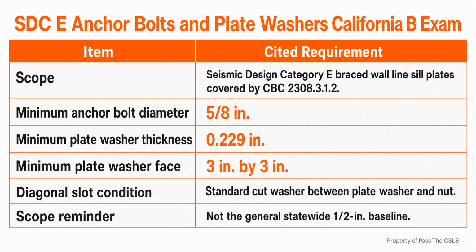Section R502.2.2 addresses subflooring that serves as a horizontal diaphragm. The panel edges must be blocked, and the blocking must use utility-grade lumber or better. The practical point is that adjoining panel edges need continuous support so the diaphragm can act as a connected surface rather than as separate sheets moving independently. I do not memorize a universal nail size or spacing for every shear condition, because the research for this lesson does not support one statewide schedule that fits every engineered design. I verify the edge and field fastening against the approved plans and the applicable schedule.